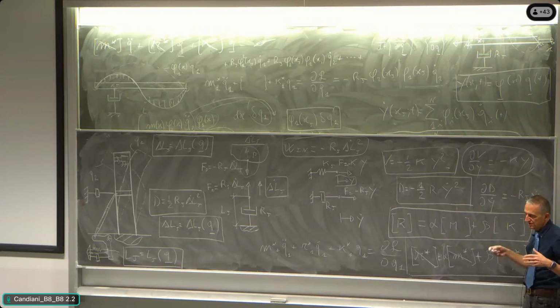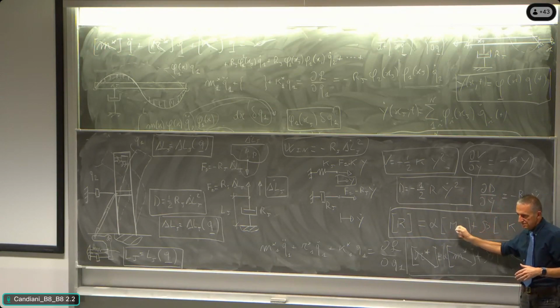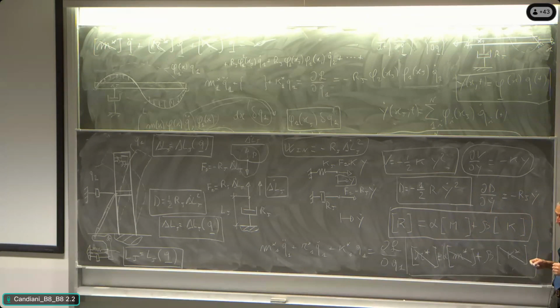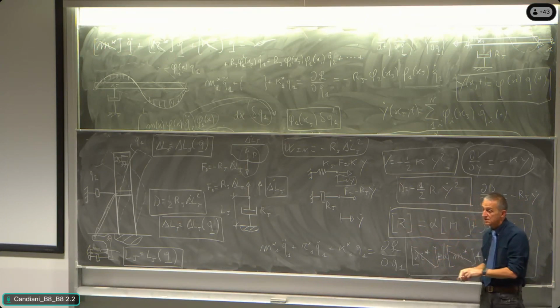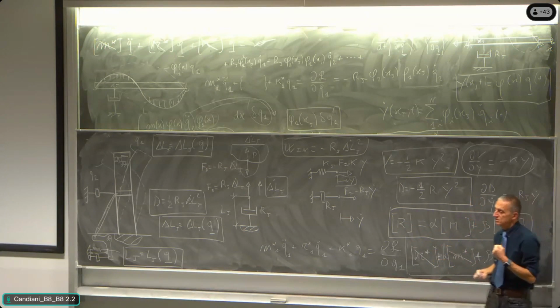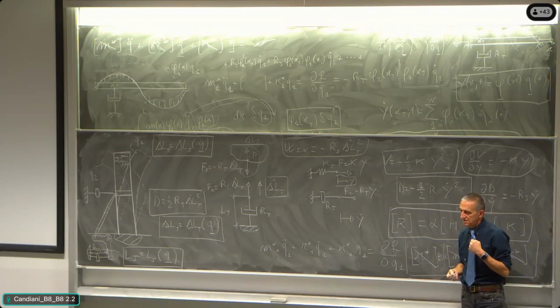You made a finite element code with thousands of coordinates, and you calculated those mass matrices, those stiffness matrices. And you would like to stay in those free coordinates and work with a damping matrix written in those coordinates, but that makes sure that if you are moving through principal coordinates, this damping matrix is not coupling the modes.